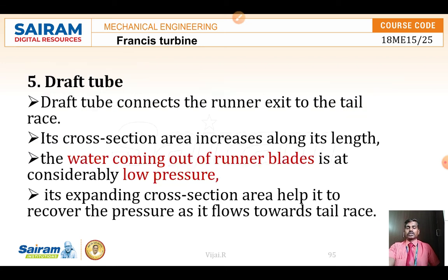For the reaction force, the blade itself acts like a nozzle. Here there is no separate nozzle as in the case of the Pelton wheel turbine. The blades themselves act as a nozzle, and when water flows through the blades, it creates a back pressure reaction on the blades, so it continuously rotates.